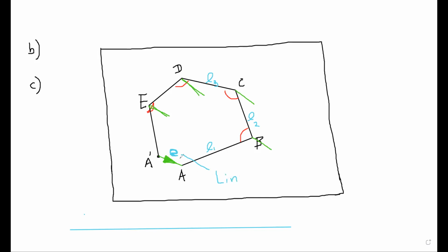Linear means length, because now we have corrected all our angles. All angles are corrected. Therefore, this error we can totally claim on length measurements. You have two sets of measurements, angles and lengths. Angles are corrected and still you get some error. If the angles are corrected, then the total responsibility will be on length.